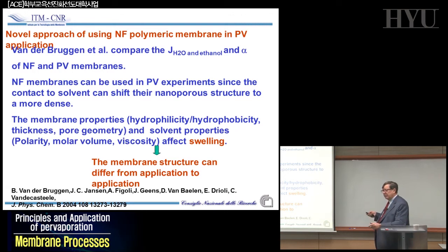And at one time, membranes were only utilized for desalination, so people were looking for 99.9 percent sodium chloride rejection for big desalination plants. Today, the interest is much wider than this, and people are looking at how to separate amino acids or a lot of pharmaceutical or biological products from salts, because this is the final purification of different fermentation processes, etc. So more and more people are interested in nanofiltration because they can separate sodium chloride, water, solvent, etc., and concentrate the bioactive compounds.